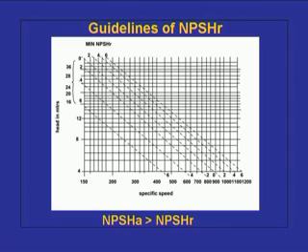If the actual pressures are not meeting this minimum NPSH required, then cavitation is likely to occur. The pump manufacturers will insist on the installation of the pumps or the design of the suction side such that this NPSH required is always met, that is, the actual net positive suction head should be more than the minimum net positive suction head, or the NPSH required.